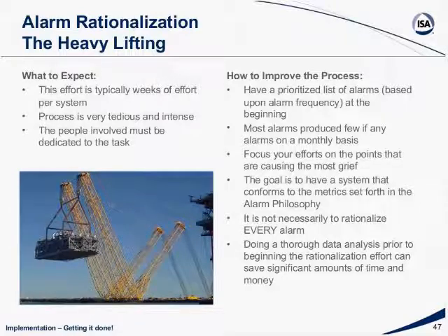And you may do half of the overall number of tags in your facility. You may do 3/4. You may do 1/4. But you don't have to do every one. Remember, the purpose here is to make the system manageable. One alarm every 10 minutes. If you achieve that after 2 weeks of rationalization, that is success. And so you really want to have a focused approach to this based on priority, okay?